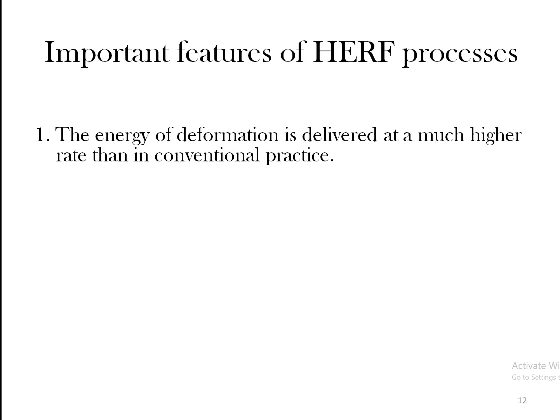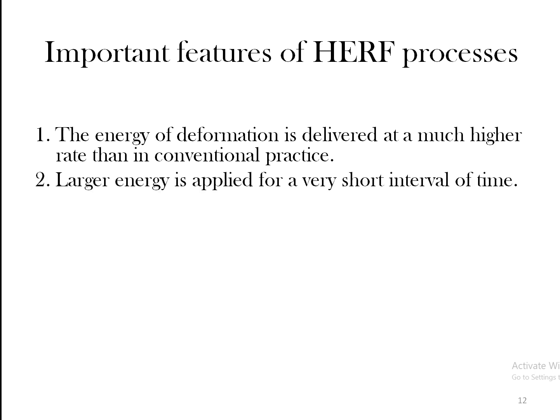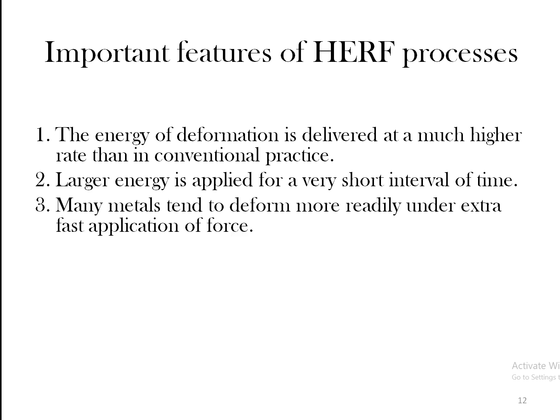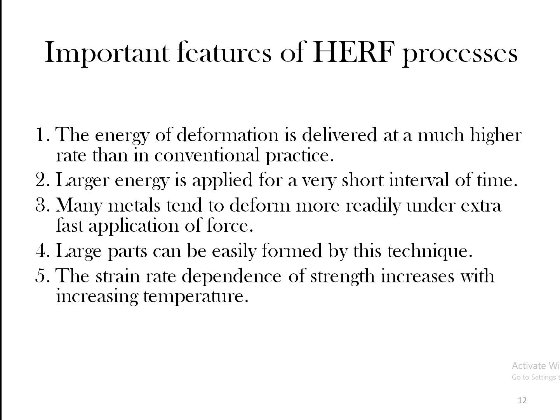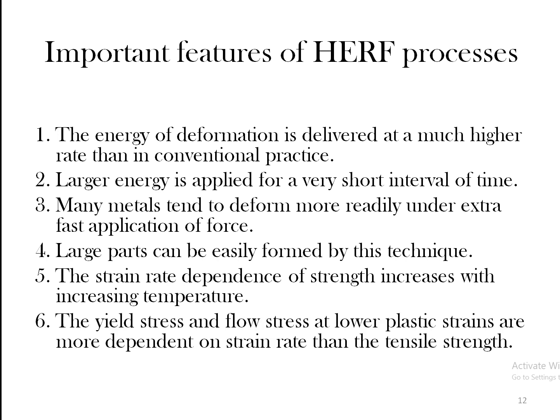So the basic feature of the HERF process is that the energy of deformation is delivered at a much higher rate. That is, a large energy is applied for a very short interval of time. Because of this, many metals tend to deform more readily under extra fast application of force. Many metals like aluminum alloys and high strength steels can be formed using this process. Large parts can be easily formed, and even complex shapes can also be formed using this method.